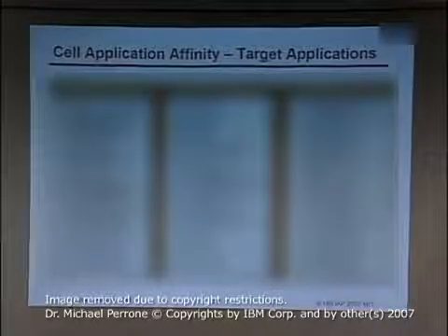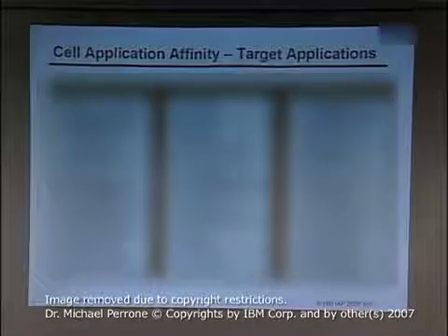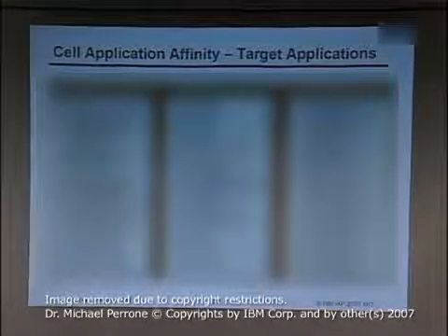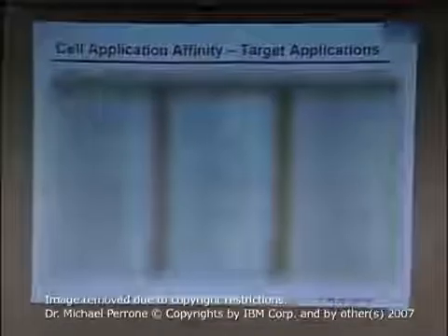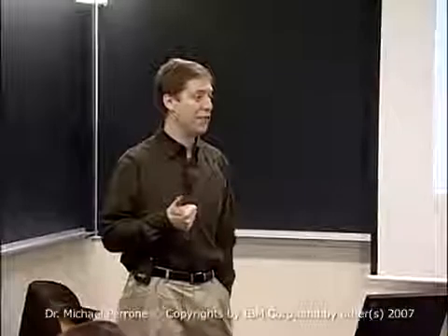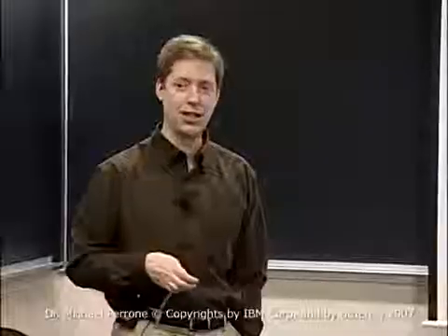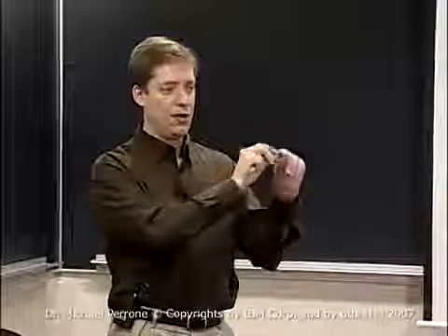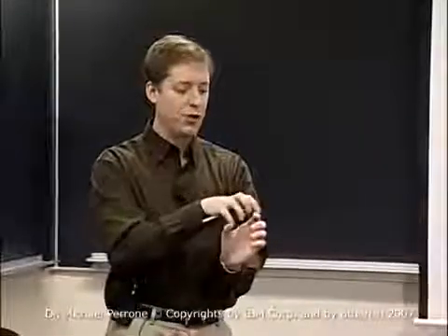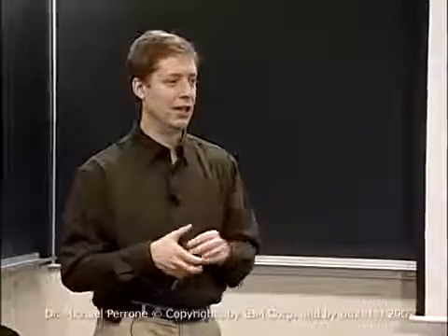Signal processing, image processing, audio resampling, noise generation. You can read through this list. It's a long list. And I guess there are a few characteristics that really make it suitable for Cell. Things that are in single precision, because we've got 200 gigaflops of single, and only 20 of double, but that will change, as I mentioned. Things that are streaming through, and so signal processing is ideal, where the data comes through and you do your compute and then you throw it away, or you give out your result and you kind of throw it away. Those are good.